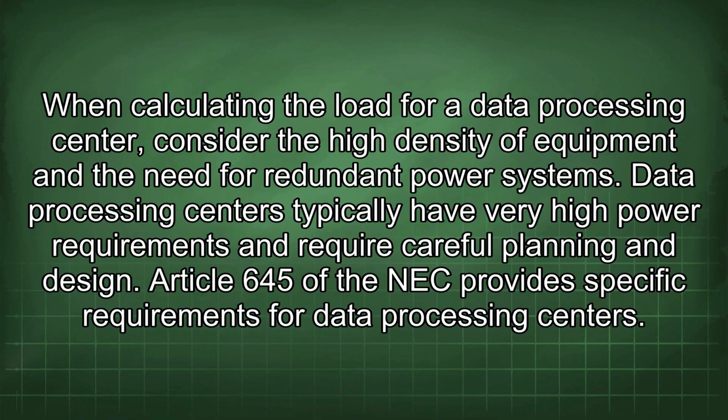When calculating the load for a data processing center, consider the high density of equipment and the need for redundant power systems. Data processing centers typically have very high power requirements and require careful planning and design. Article 645 of the NEC provides specific requirements for data processing centers.